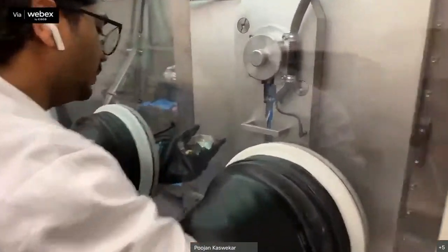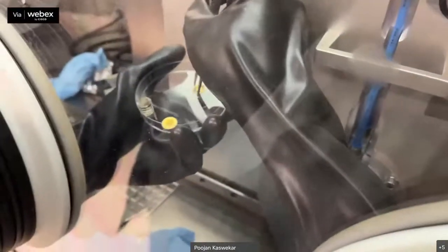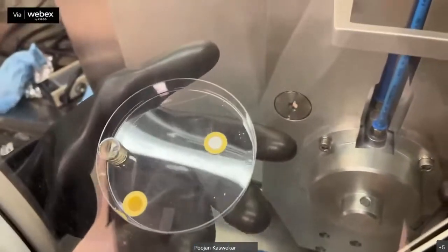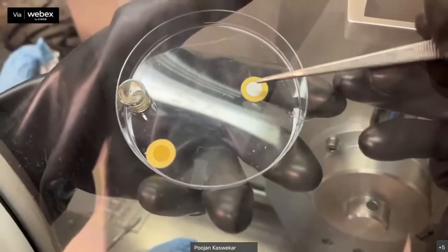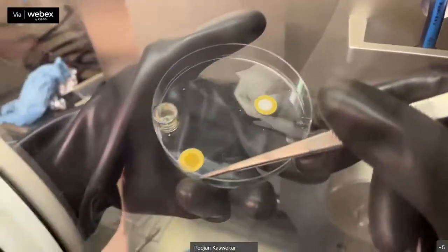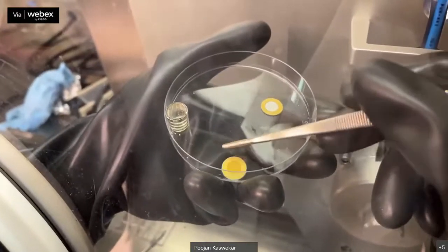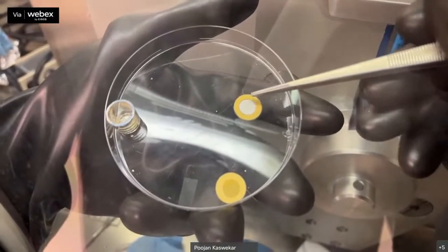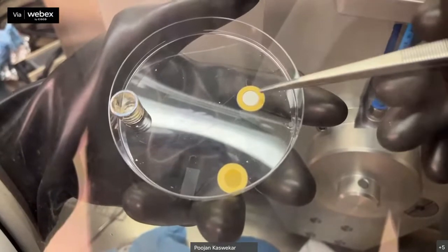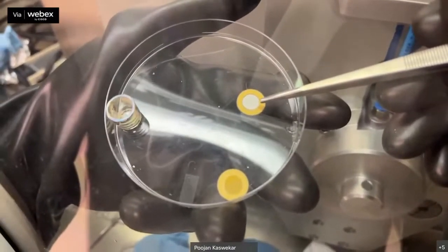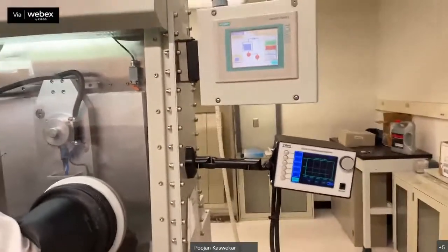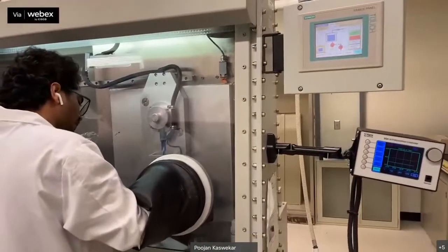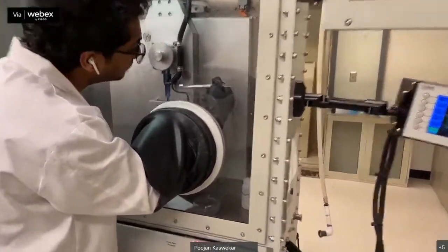Somebody asked a question before, when do we know we need to change the sensor? You can see the difference between the sensors, the deposited one. There is a lot of silver deposited on this sensor, whereas on this sensor there is not much. We change this sensor because its life is low, as a lot of deposition went on top of it. This one is okay. You can see some silver is deposited on top of this one too.